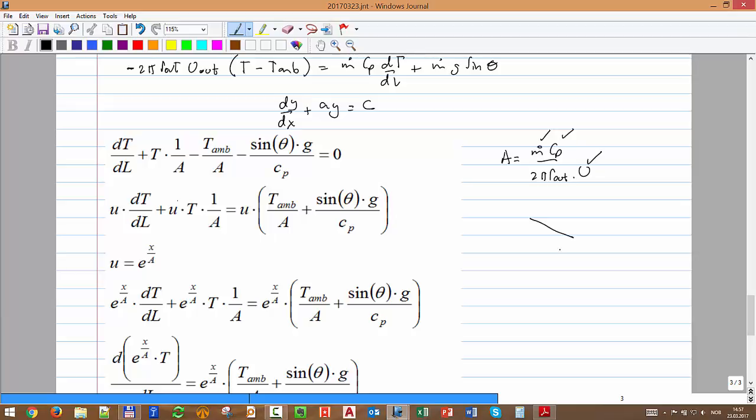If I have, for example, commingling of 3 wells, I have to apply one equation down to here, one equation down to here, then I have to make a mixing, that if you remember, the equation is just 3 things that come in and 1 that comes out, M1 H1 plus M2 H2 equal M3 H3, and then I progress again on that section.